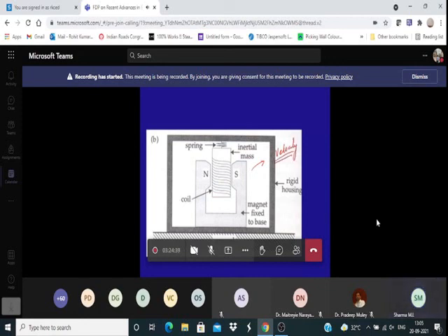Earlier, the manual and other oscillograph types are all displacement meters, and all the seismometers are basically velocity meters because of the change of mechanical vibrations to an electromagnetic signal. And once it is electromagnetically available to me, then what I can do is go for the amplification of this. That is much easier than for this.